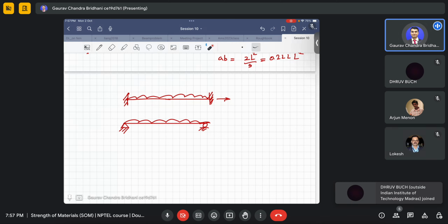Now, about the usability, or which one is good. Obviously, if you are making a structure, first of all the most important thing is the restraint. We draw it very easily; it is very easy to put these bars and say that it is a fixed end. But how to achieve it in reality is more difficult, because we have to provide that much rigidity to have a zero slope for a considerable length.